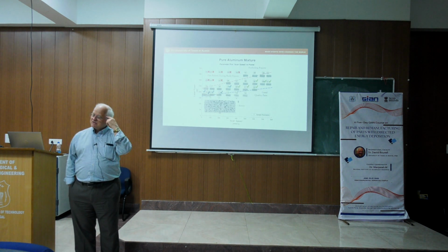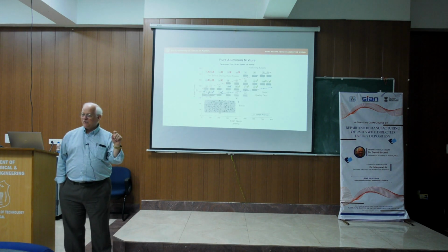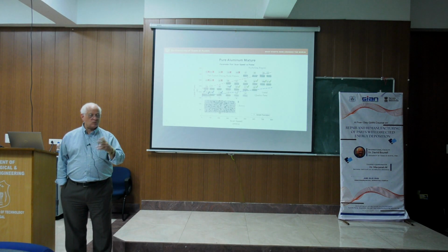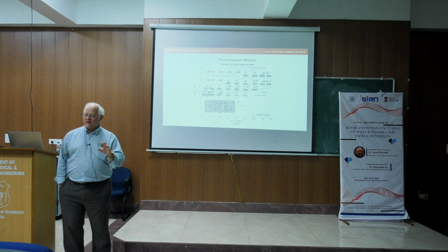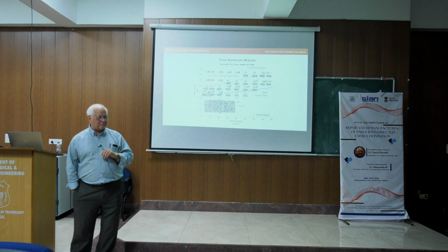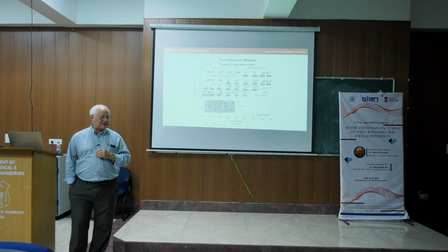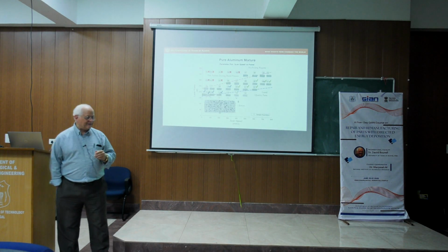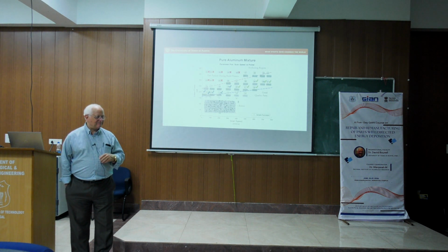And so I always think of this when I look at additive manufactured parts, where they're showing deviations of 5 to 10% in the X, Y, and Z direction. I always think back to these plots that show 3,000 or 4,000 tension test samples on raw material, where again we're seeing plus or minus 10% variation in the mechanicals. So basically my first answer is, maybe it's not significant.